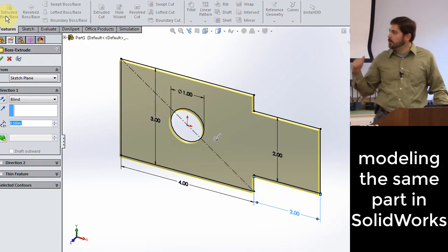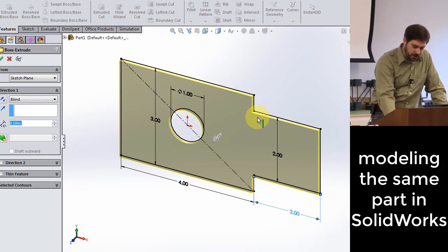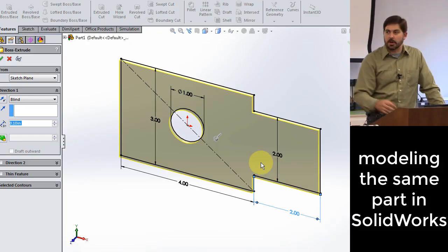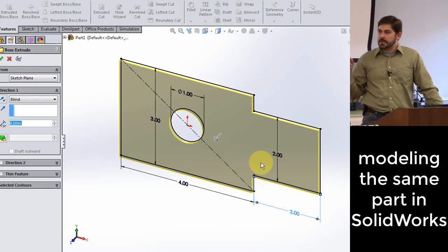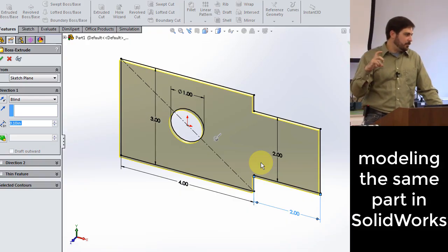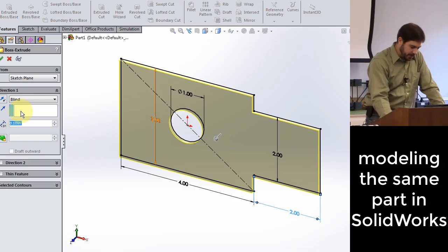And some of you might be wondering, on the original that I had fillets. I had little curvy things on these interior corners. I left those off at this stage on purpose because one of the things I'm going to play with after a little bit is changing the values of those, and it's easier to do that if you use an actual fillet feature at those locations instead of drawing it into the figure. So anyway, just to explain why I'm doing what I'm doing there.